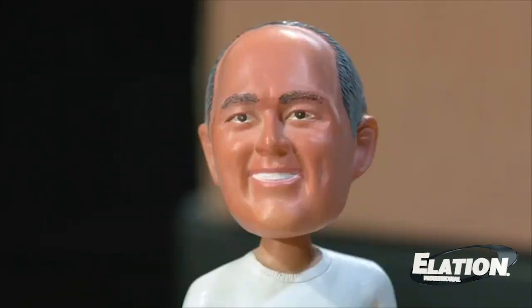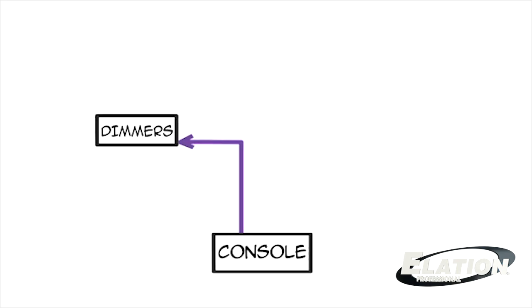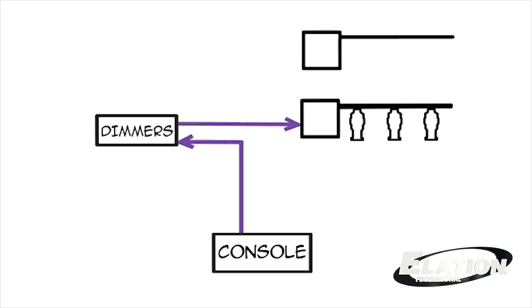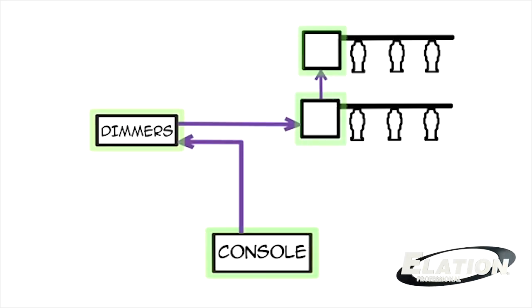I find your lack of faith disturbing. What? Sure, a lighting network is different from DMX, but the similarities can serve as your starting point. All right, Shorty, show me. In your DMX system, the console called out data to your dimmers and other devices in one big pipeline. All the data got reported to all the devices. Every device had a unique address, so it knew what data to react to, right? That's right. Easy to map.